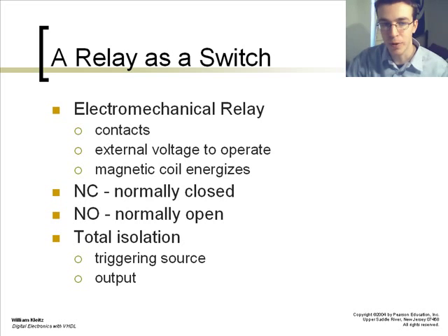Say you have a motor you wish to operate and you have a relay as a switch, you'll have a microprocessor taking that value from your microprocessor, turning it into an on or an off signal, which turns on your motor. You have 2 types of relays. You have your normally closed and normally open. This determines whether, when you have your on voltage, you want the motor to be on or off correspondingly.